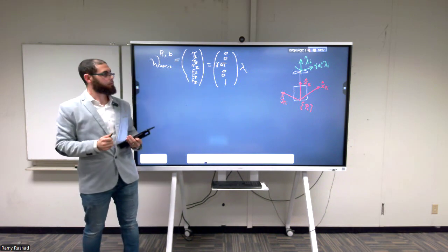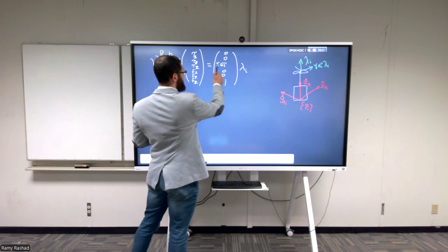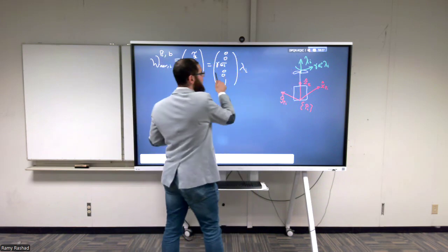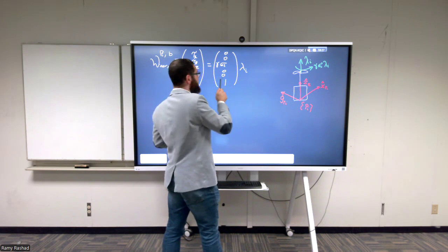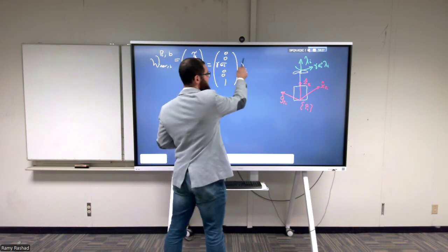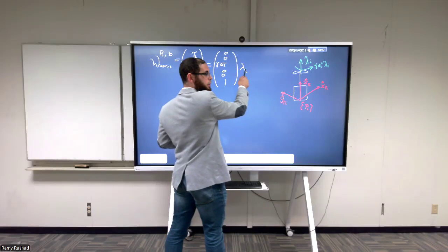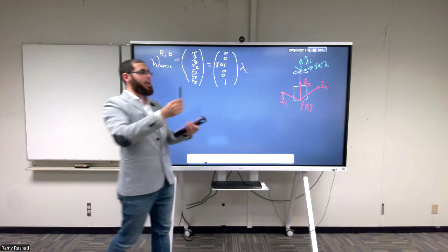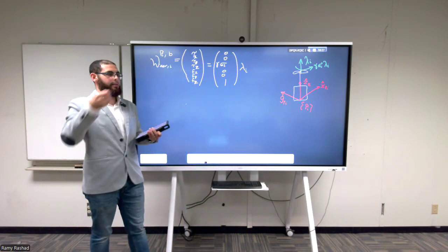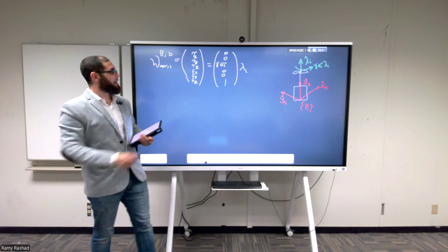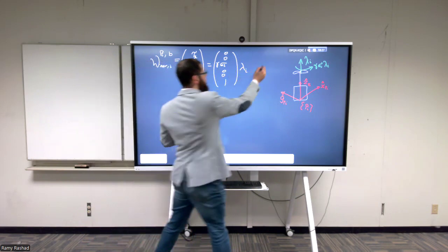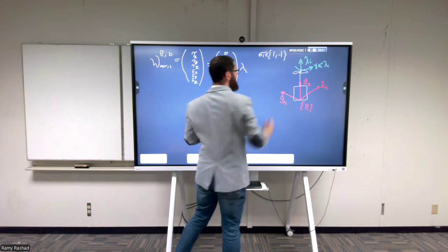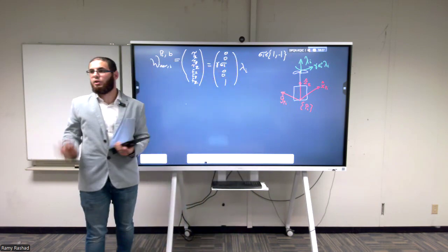So what is lambda? What is sigma? Lambda is the thrust that's produced. Gamma is the constant that when you multiply it by something that has force units, Newton, will give you Newton meter in the end. So it's the proportionality constant between the drag torque and the propeller thrust. And sigma is just a direction. So sigma I is a number either 1 or -1, okay? Depending on whether it's counterclockwise or clockwise. It's just a convention.